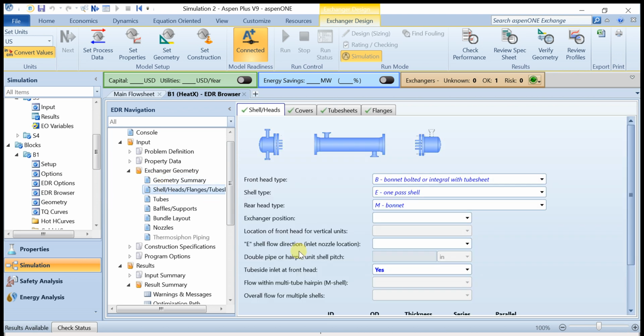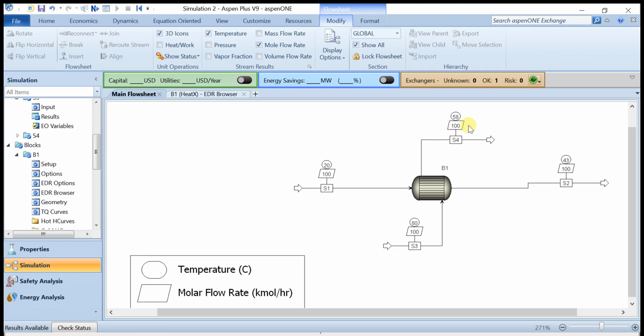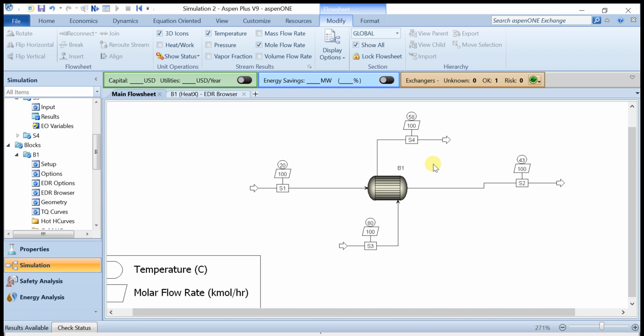But for calculation, the number of tubes are 40. For the setting plan and the tube sheet layout, the number of tubes are right now also 51. So I need to decrease this shell ID such that I will get that reduced number. So we can do this exercise offline, right? Okay, now before just closing, there is one very important thing which I wanted to show you.